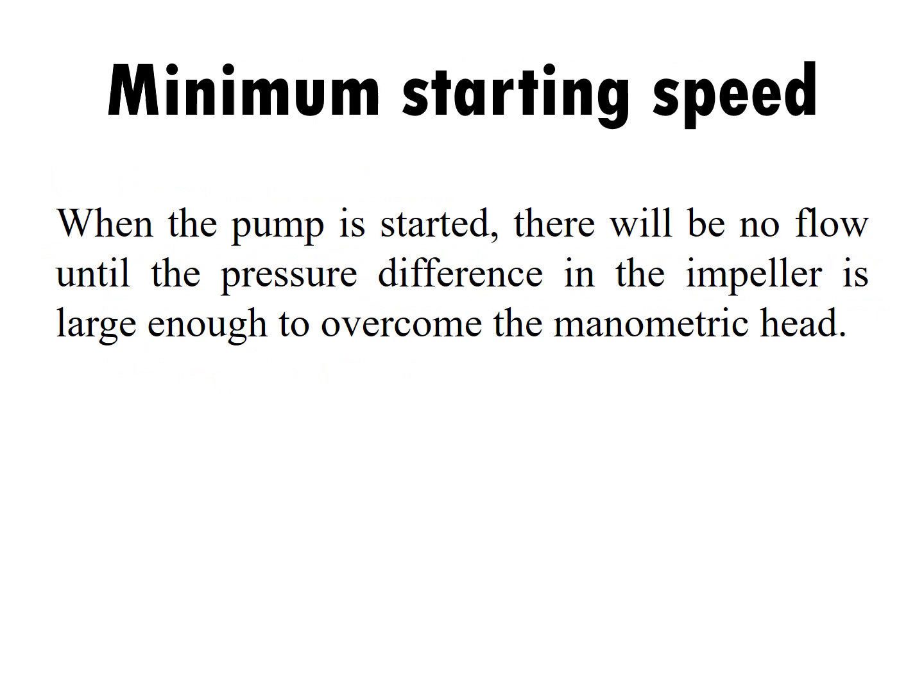Now, what is minimum starting speed? When the pump is started, there will be no flow until the pressure difference in the impeller is large enough to overcome the manometric head. So the minimum speed that will be required when there is no flow and for the pressure difference to take place is known as minimum starting speed.